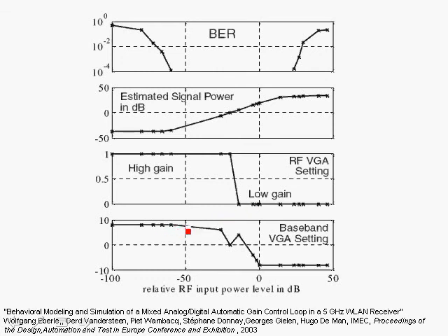We also notice that the baseband VGA gain setting is changing. We had a range between -8 dB and +8 dB in 2 dB steps, and we see that the VGA starts to kick in to adjust the gain so that we can meet our target RMS value. At a certain point, when the signal power is too large, we actually have saturation and the bit error rate goes high. So this set of curves illustrates the operation of AGC in order to achieve a wide dynamic range in, for example, 802.11a or 802.11g.